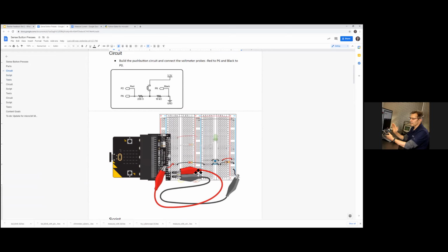Well, yeah, it's a habit that we developed because back in the Basic Stamp days, there were a certain number of I/O pins that were burned up by not having a 220, accidentally having a wire, and maybe your code would send high and low signals through the pin. As soon as you press that button, when the pin is sending a low signal from a previous program, it would pop on a Basic Stamp. And so we'd end up replacing those at a discount. So to try to minimize that, we throw in that 220.